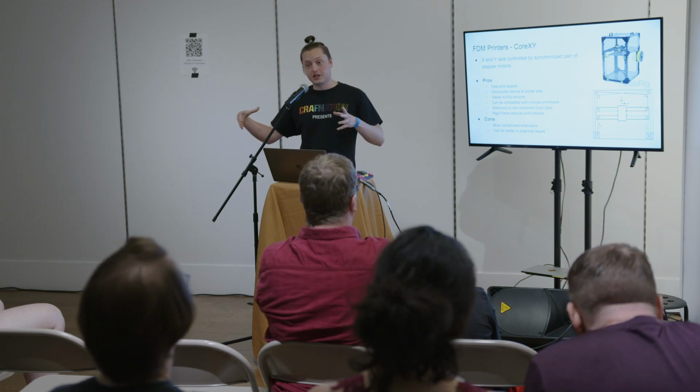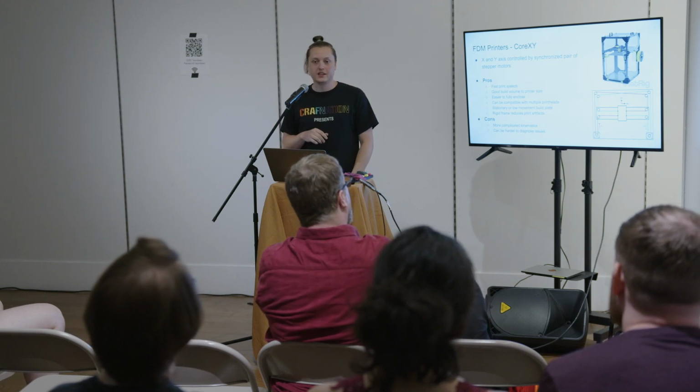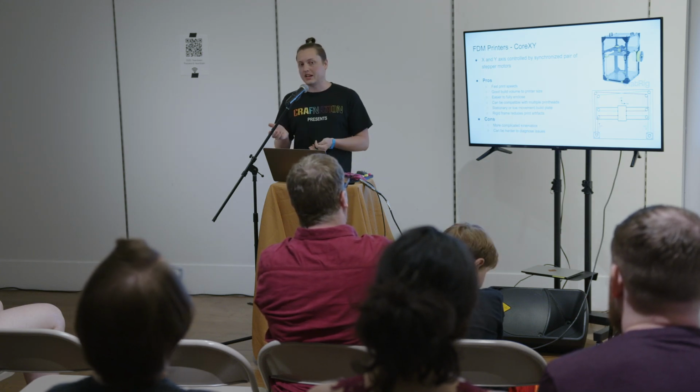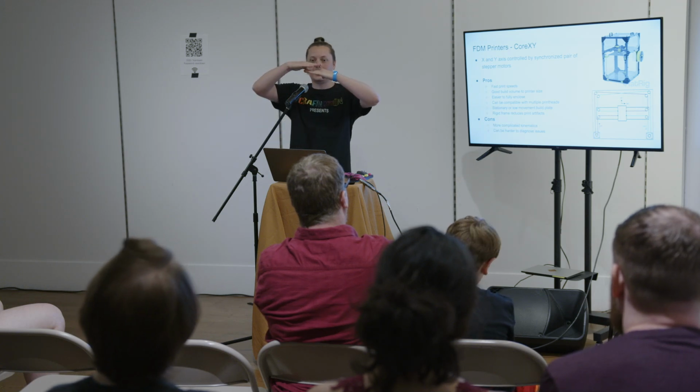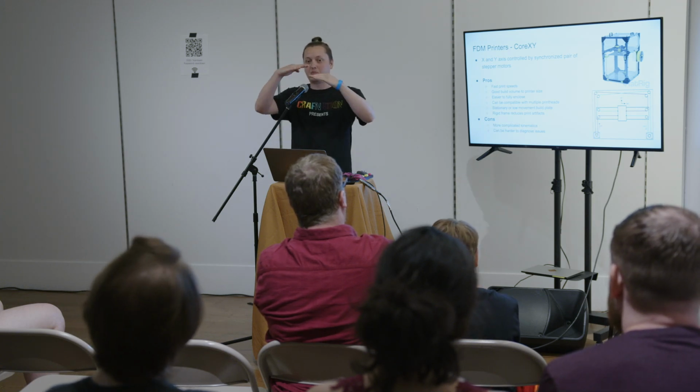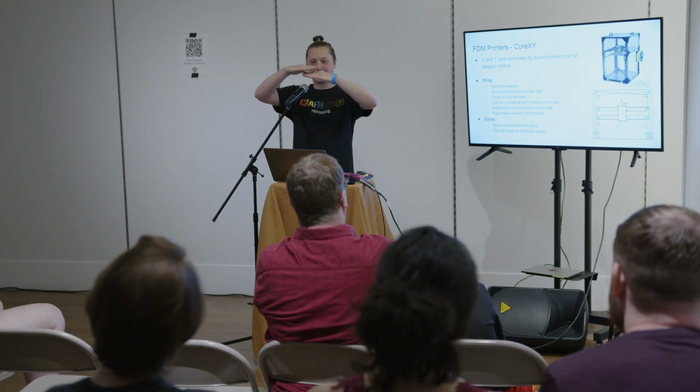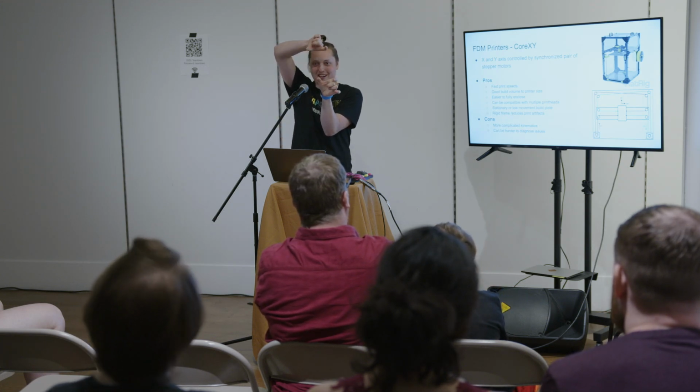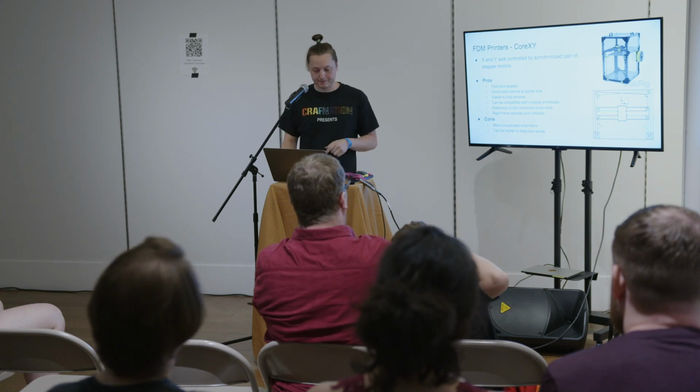They also tend to have a much more rigid frame construction due to the number of points that they're built around, which allows more rigidity, which prevents things like print artifacts that can show up on your prints. That can be anything from your layers shifting, where something happens and part of the print is here and then it shifts a millimeter and the rest of the print will be off. It helps reduce things like that.